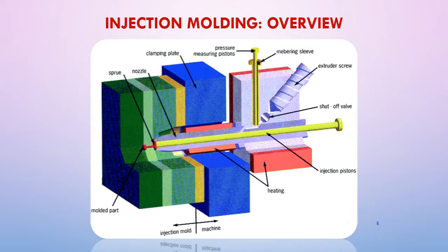So here is the picture showing the injection molding process. These techniques play the dominant role for production of micro components of low viscosity polymer. During this process, high pressure around 50 to 200 MPa is applied to inject the polymer into the microcavity. The microcavity represents a blind hole which is filled from the face. This is the molded part that we want to produce here.